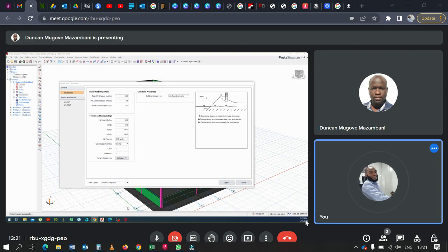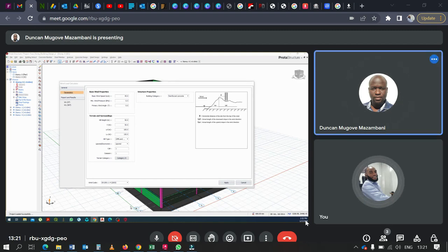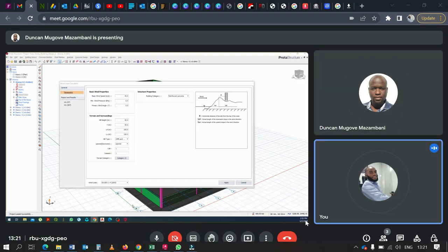On this diagram showing here, you can see that wind direction hitting the building. So the hill height here simply means if you have, let me say, since this is a 4-story building, if you have something like a 3-story building around the place where this building is to be sited, or 2-story building, so that building now acts like a hill height.